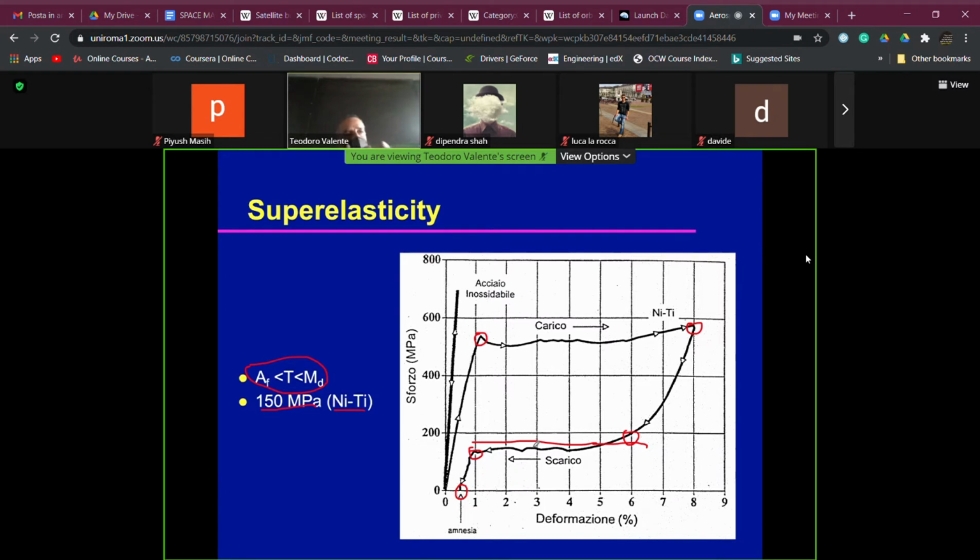So the response of the shape memory alloy is not very fast, and it can be used for cycling movement just if we have a few hertz of frequencies to be satisfied. If we are thinking of fast actuating movements, we need to change the material from the nitinol shape memory to the piezoelectric materials, which we will discuss in another lecture.